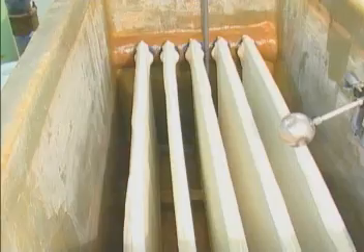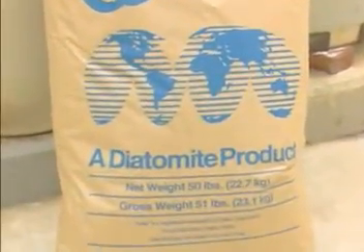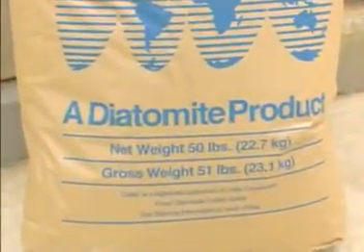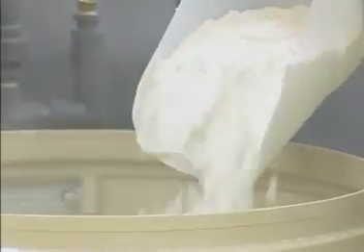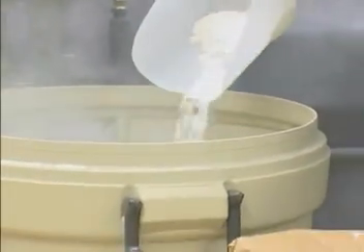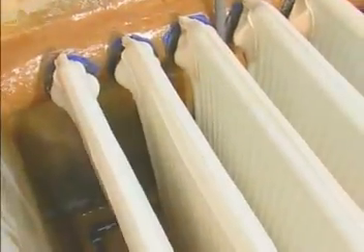Plenums are covered with a permeable material that allows the free flow of water. DE is the skeletal remains of single-celled plants called diatoms. There are differing grades of DE based on pore size. Usually, the pore size on the plenums is matched to a particular grade of DE.